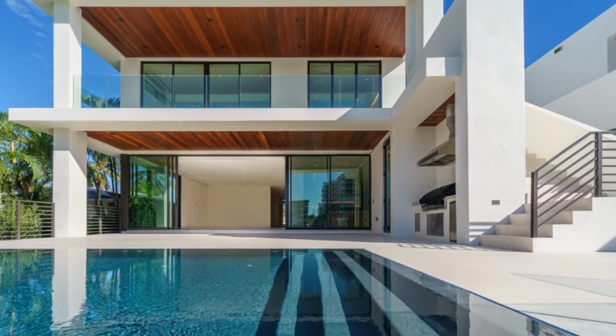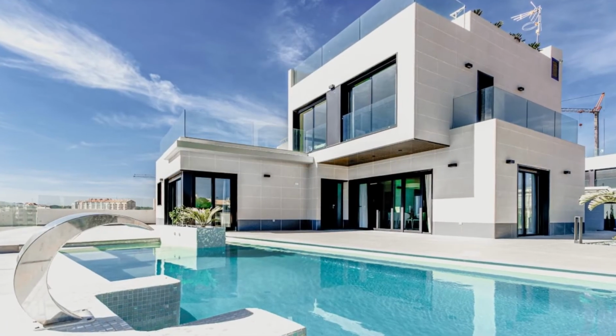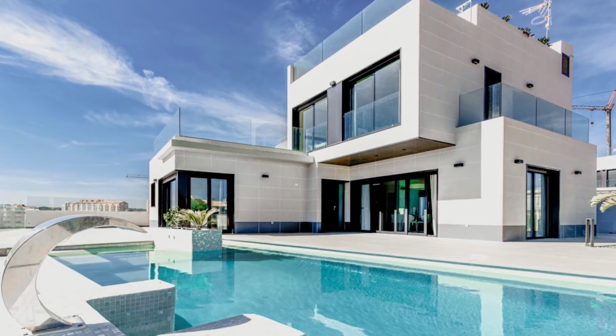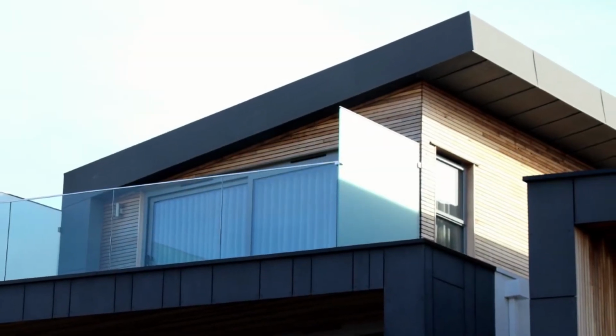Number 8. Now, a lot of people like super cantilever decks. If you can't bear having a post to support a balcony or a deck, get your builder's engineer to design a self-braced system. It ends up with less material where that deck connects with the building's wall, bringing down the cost substantially. Additionally, makes it less cold at that threshold during the winter.